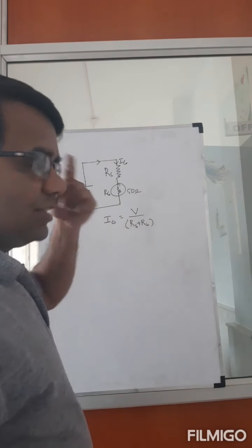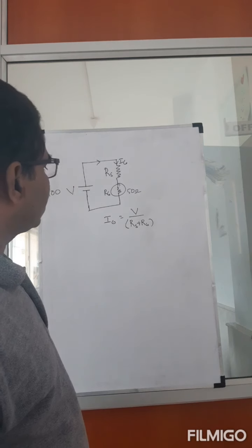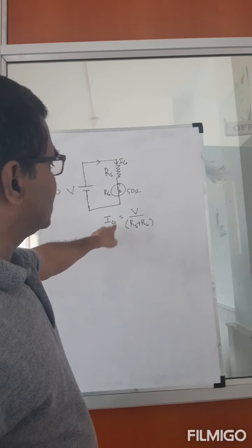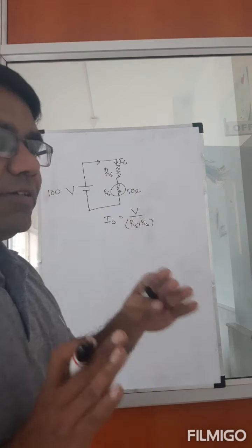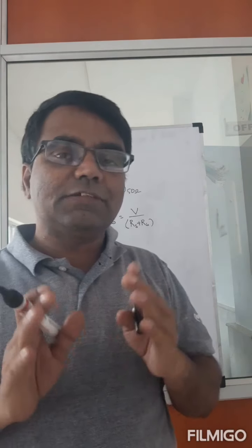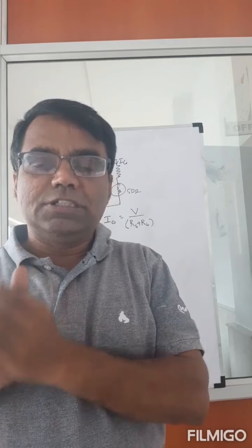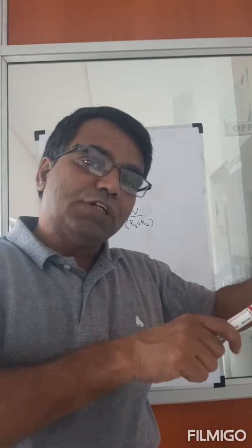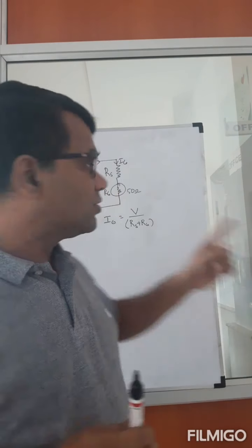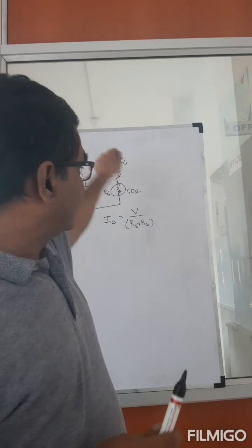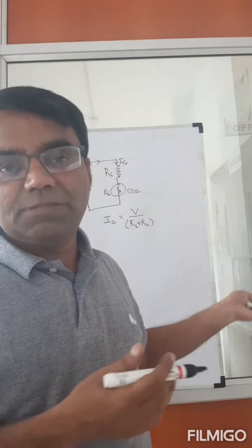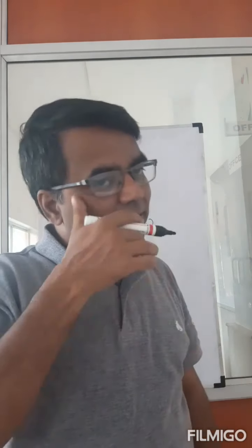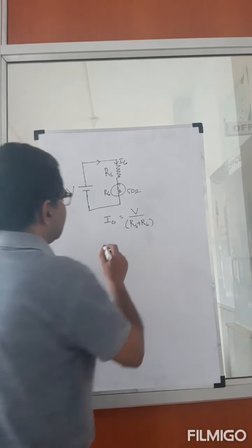So this is the general equation now, right? This has to be 20 microamps for full scale deflection. So if you want to create a voltmeter which has a range of 0 to say 10 volts, then when it is 10 volts, the galvanometer should show me full scale deflection. So when there is 10 volts connected here, then the current through the galvanometer has to be the maximum current that's allowed. In this case, it's 20 microamperes. The galvanometer that we have taken is 20 microamperes.